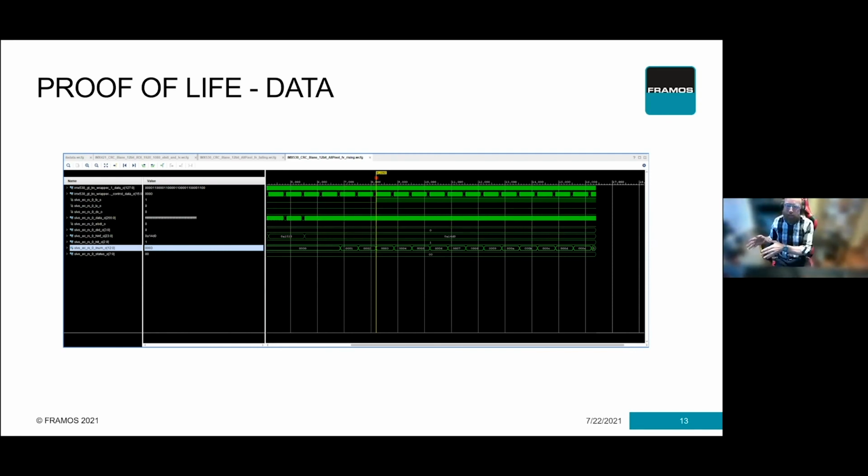And if you look back in history, everyone had CCD, so everyone was a whiz with the analog design and taking care of it. Then everything went over to CMOS, and then it became high-speed data connections, and that kind of power supply stuff dropped off. And also we have many more noise sources now inside that world. Sharing power supplies between main FPGAs, RAMs, and the sensors is something you should not do.